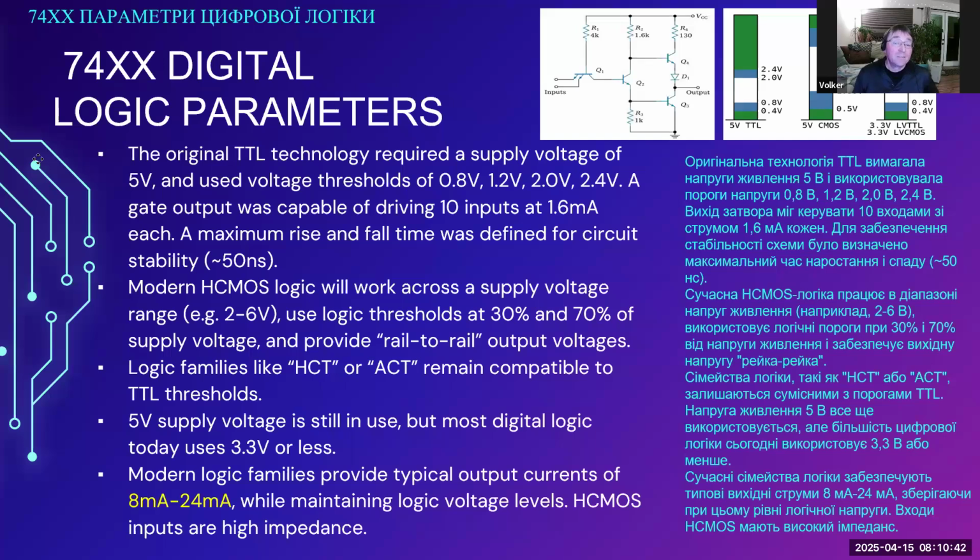I'm emphasizing here current output while maintaining voltage levels, because you can pull more current out of the outputs, but then the TTL or logic output levels aren't guaranteed. And of course, at some point one would have to make sure that the maximum allowable values aren't exceeded.